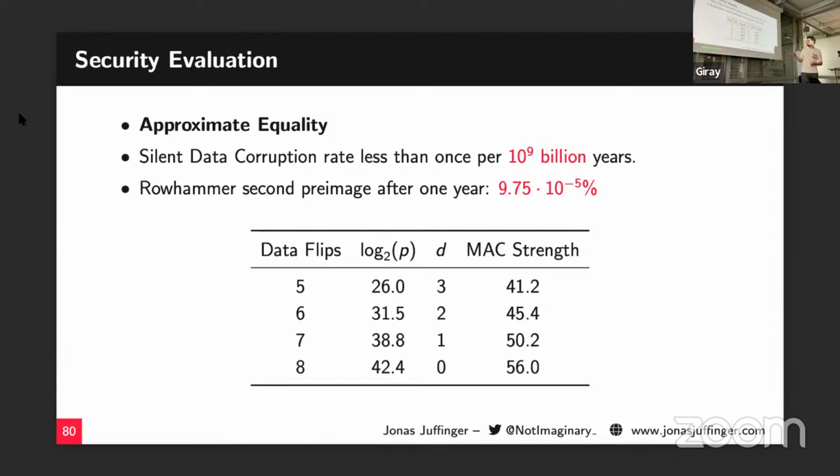No, this is the thing I showed before. When comparing the MACs, what we do is we XOR the two MACs, and then we do a pop count to see how many ones we get. If the MACs are equal, everything is 0. And if we look for 5 or fewer bit flips, we allow the pop count to be up to 3. So we just allow any 3 bits to be different.